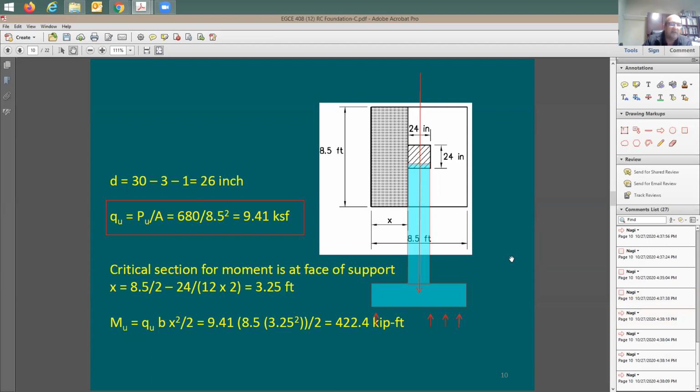Now, where is the tension side? When any deflection or deformation is going to happen to the footing, which side is it going to happen on? The tension side is going to be at the bottom because you're pushing this up. It's true that this is the axial load coming; this is going to be the applied load, and this is going to be like a reaction.